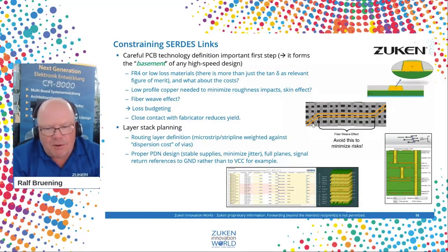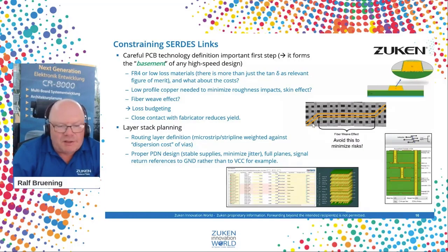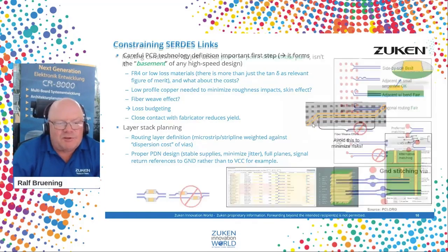Another important aspect: the power distribution system has to be designed pretty carefully, so power integrity simulation may be beneficial. Full planes are recommended, and a proper planning of the current return path. Current has to return to its source.